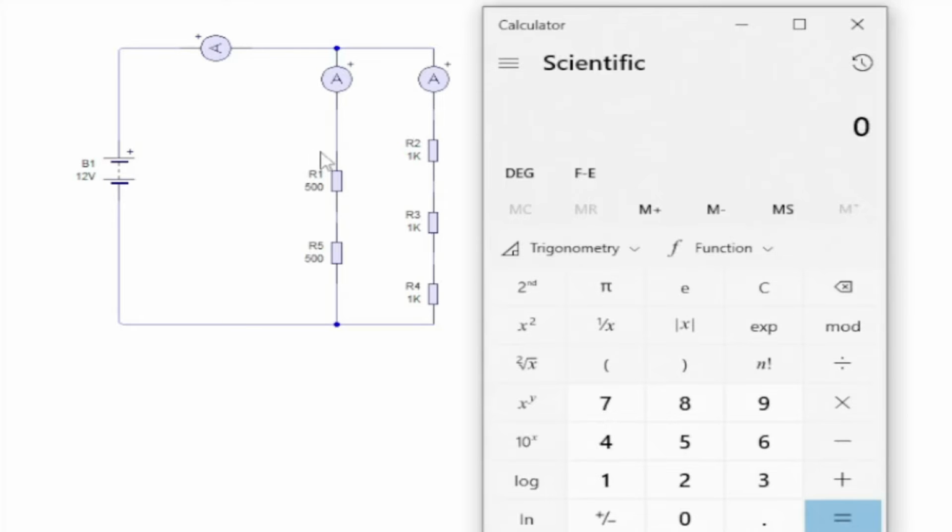So first of all, let's find the total current in this circuit. In order to do that, we need to find the total resistance of this circuit. And before we can do that, we'll need to do two equations actually. We'll need to add these resistors up, because these two resistors and these three resistors here are both in series. As I keep saying, like a TV series, it comes on one after each other. We just simply add them up to make one big resistor.